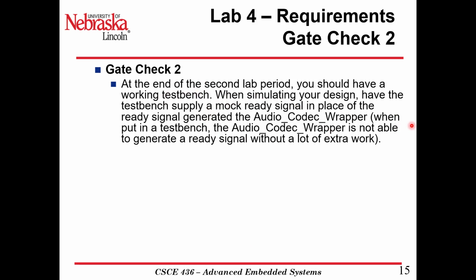At the end of the second lab period, that'll be after spring break, you should have a working test bench. And I have an example in the slides to take a look at so you can get an idea what it's supposed to look like when simulating your design. You're going to have to generate a mock ready signal in place of the ready signal generated by the audio codec wrapper.